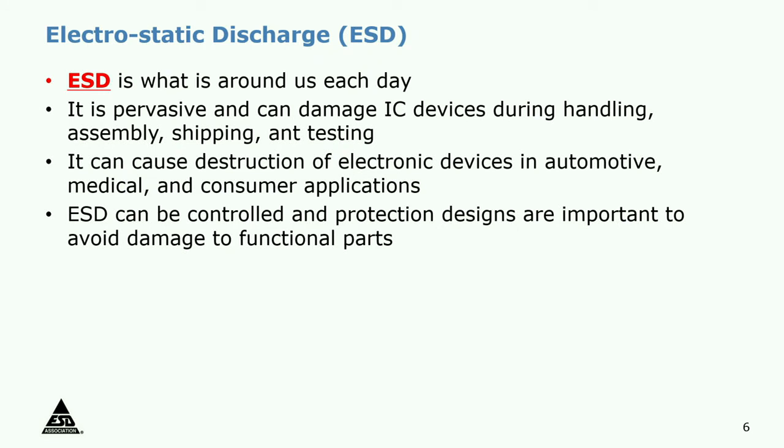So ESD can be controlled. If you don't control it, there are just going to be tens of thousands of volts everywhere, discharges, and you can't do anything about it. In fact, you can't build any electronic devices if you don't know how to control it. Even if you control it, you can't make it go away. It will be some minimum level you can control to, and based on that level, you have to build protection circuits at the IC chips to absorb this external ESD threat. That is, simply you place some kind of diodes at the IC pins so that they can clamp the voltage and protect the IC pins.